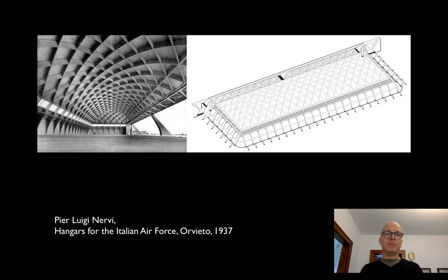One is that those ribs are stiffening the curved vaulted roof, right, and making it keep its shape as a surface active structure. The other way you can look at it, though, is as a kind of coffering, like the Roman Pantheon, where the roof is behaving as if it's 3 feet deep, but we've scooped out a lot of the dead weight of that roof and made it as light as possible. And you can see on the right, lightweight is important in this case because the roof has to be lifted up above the floor where the aircraft that it's going to shelter are going to be.